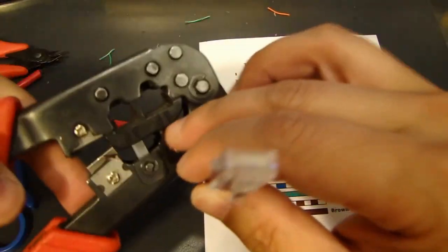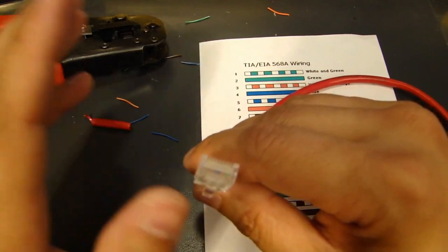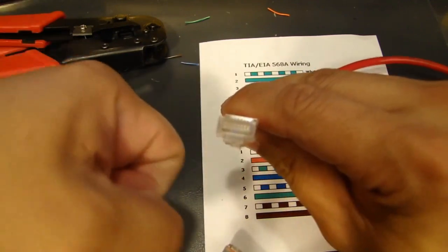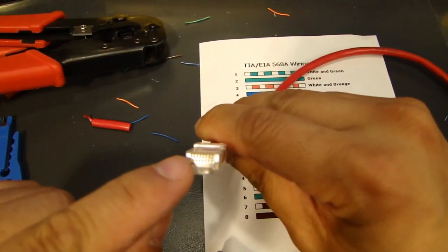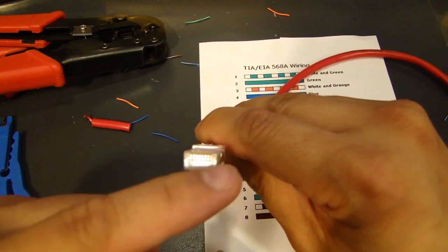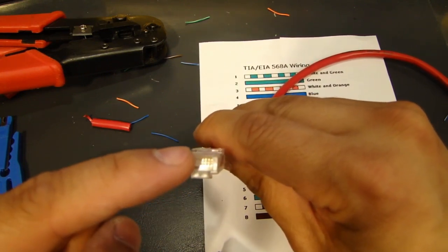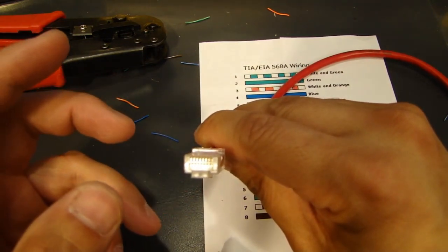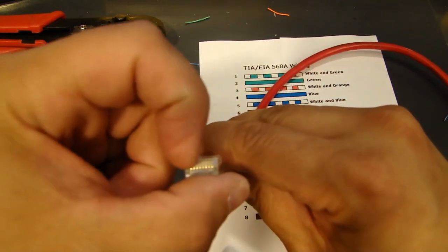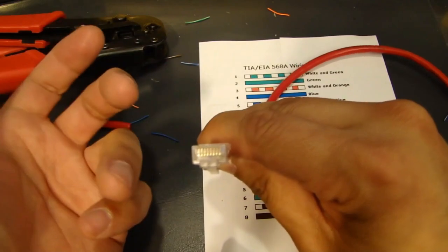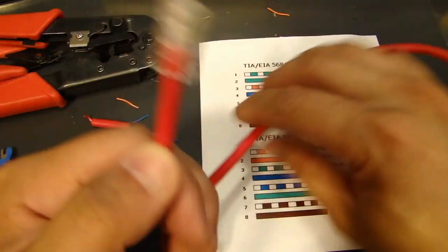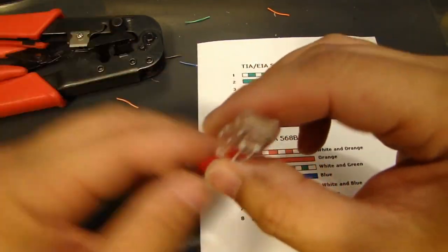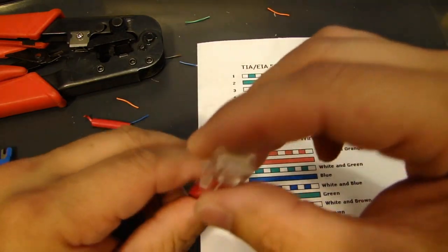The die that was on the crimper was, I don't know if there's something wrong with the die or whatever it is, but basically if you look at the end of it after he crimped it, and he crimped that thing tight, you would actually see the pins. The first and last pin is crimped down, and then it starts bowing up top near the middle. So like pin 3, 4, 5, they were actually not even crimped down onto the wire, making no contact. And he thought it was good. I mean, he made hundreds of them, plugged into the equipment. Next thing we know is that they had no connectivity, no link on the switch or the router. So we had to fix all that.